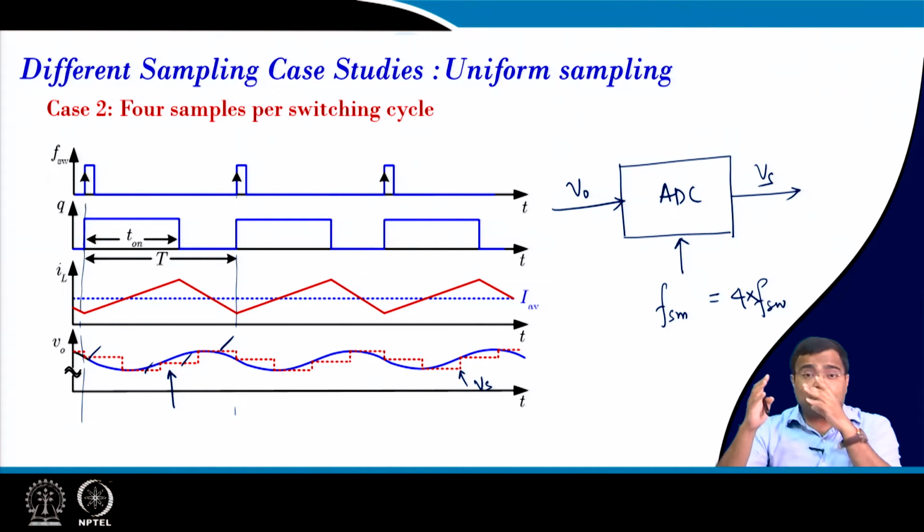I can just keep watching the ADC, and may not sample at all, and it will behave like an open loop system. In that case, we can reduce the sampling rate just to save power. That means we are taking the sample, but we are not computing the digital controller; you are just keeping it idle and holding the value. So, there are many possibilities that we can discuss.